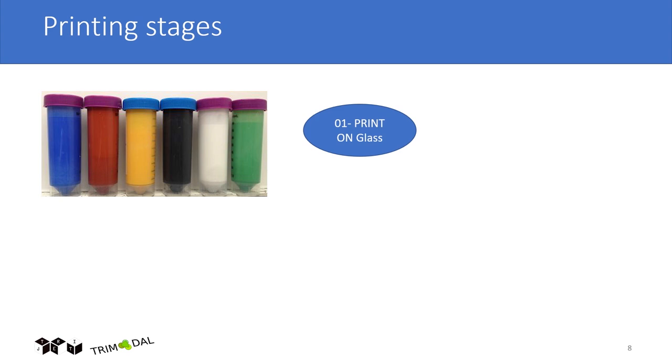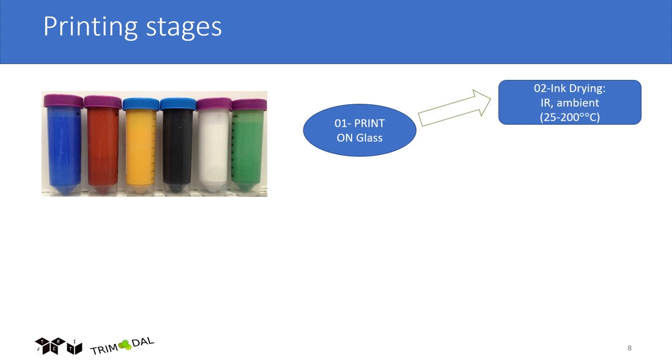Okay, so what you do, you print on the glass, and the important thing is once you print on the glass, you do the drying process, right? There's an IR lamp, you dry it quickly. But as the industry is going, some people even heat the substrate glass so it dries. In other places, because the conventional people have screen printing, it goes straight into the dryer oven on the belt, and it dries in the oven at 200.